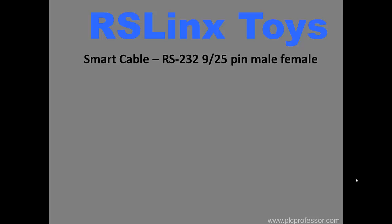This allows you to make any kind of RS-232 connection you could imagine. And then there's 3 switches on the little breakout box with the LEDs, and by putting those in the right positions, the LEDs will tell you when you have a good RS-232 connection. Okay, that's always a good thing to have around if you have a lot of RS-232 devices but don't necessarily have all the right cables.